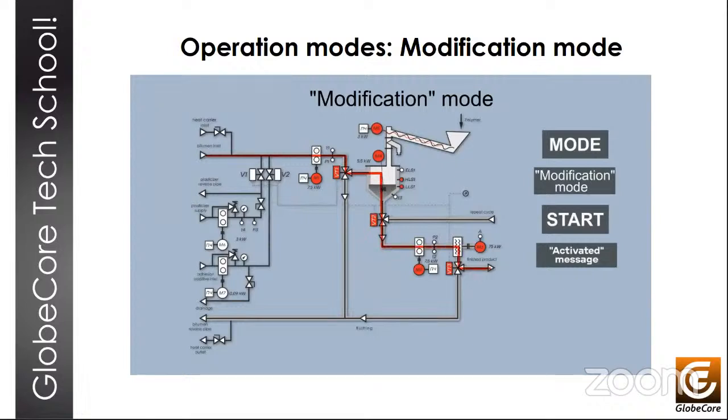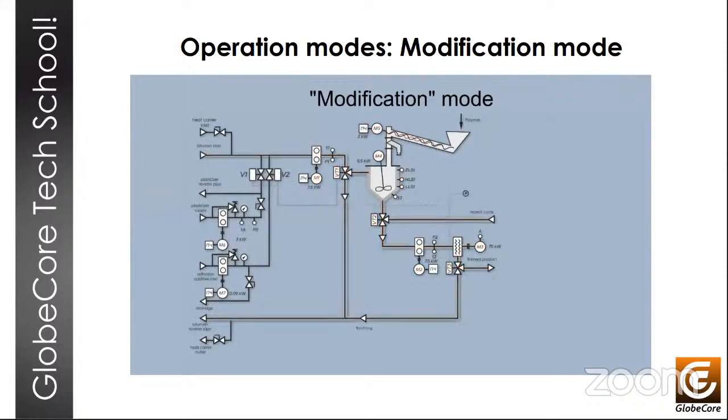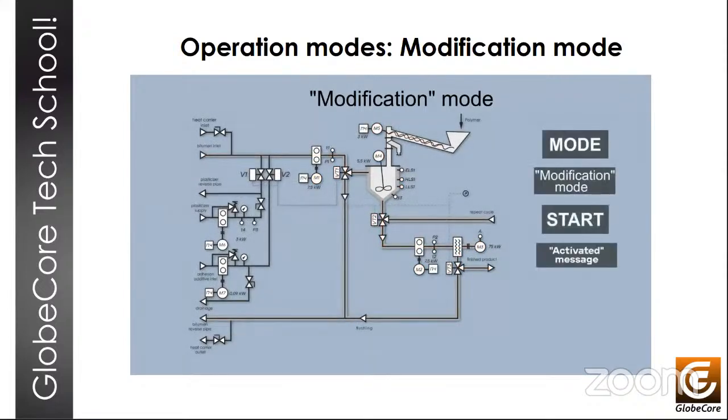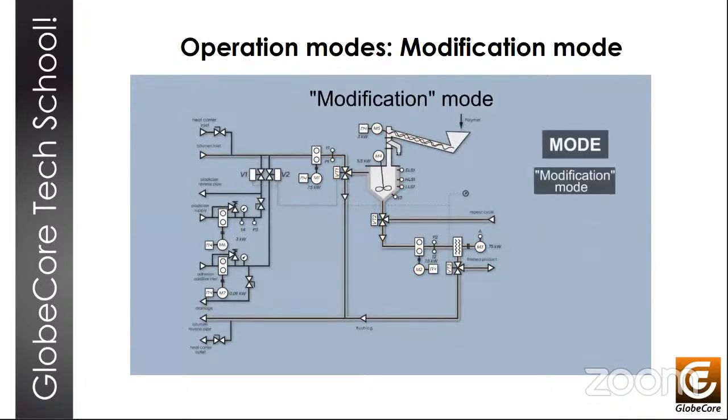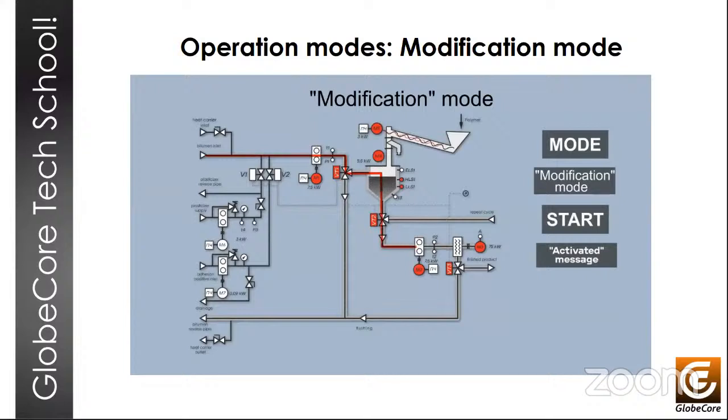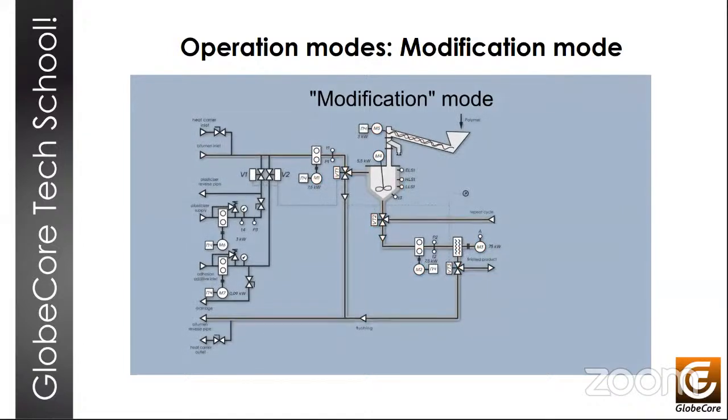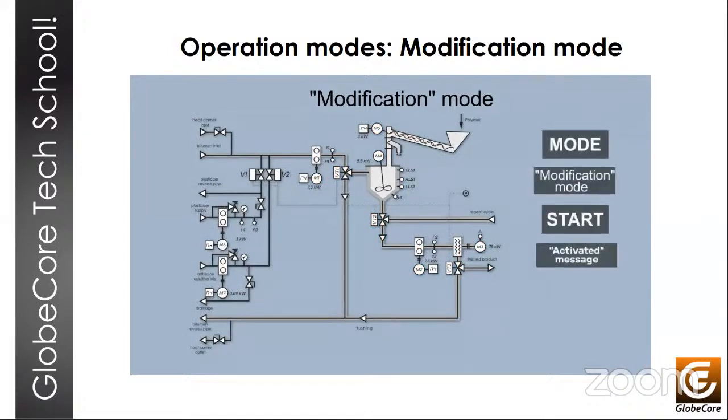So pneumatic valve VT1 switches from bitumen supply to the return line to supply to the mixer, and the bitumen supply pump M1 starts, and the mixer tank is filled with straight bitumen. So when the bitumen reaches the lower level sensor, LLS1, the M4 impeller agitator is switched on, the screw conveyor motor M5 and the M3 mill driver also started. So when the mill spools up to its full RPM, the M2 feed pump starts, and after passing through the mill and the VT3 valve, the polymer modified bitumen enters the maturation tank for storing of the finished product. Next slide, please.